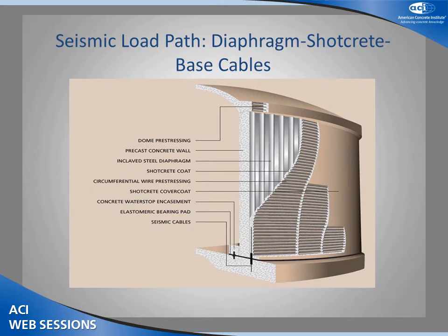Seismic load path at the wall base joint. So what we have is earthquake load acting at the center of gravity of the system, which is going to generate the base shear here, which is transferred through tangential action. And that will also result in overturning moment. So you have a tension on one side and a compression diametrically opposite. This tension, if it is exceeding the dead weight of the wall and the roof, is going to generate uplift